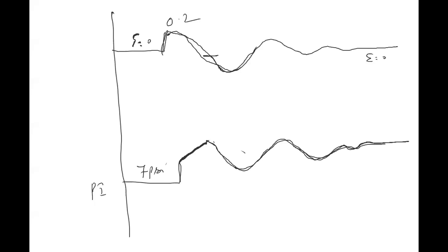So that is why you are doing the trial and error procedure. You are doing the trial: it closes, opens, slowly closes. So you can't stop exactly when you see 60, because there is a time lag of opening of the valve and it is reflecting in the temperature. What is the sequence of events?